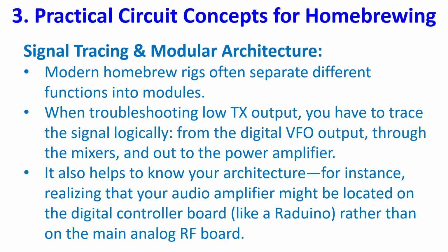Signal tracing and modular architecture. Modern homebrew rigs often separate different functions into modules. When troubleshooting low TX output, you have to trace the signal logically from the digital VFO output through the mixers and out to the power amplifier.